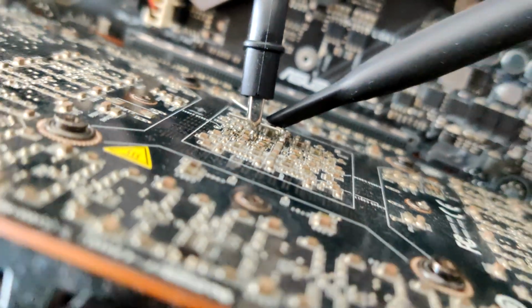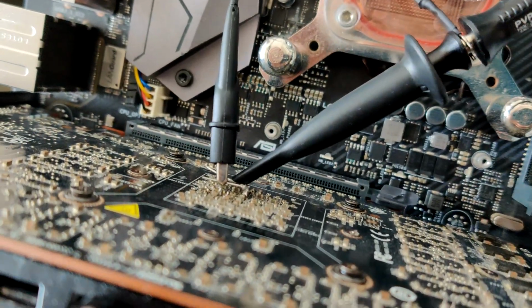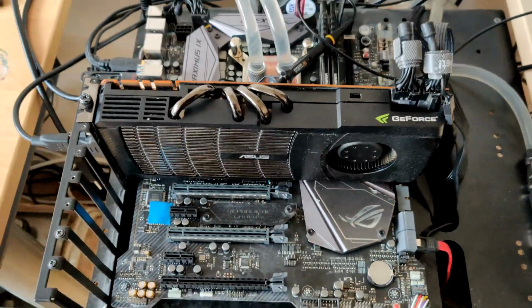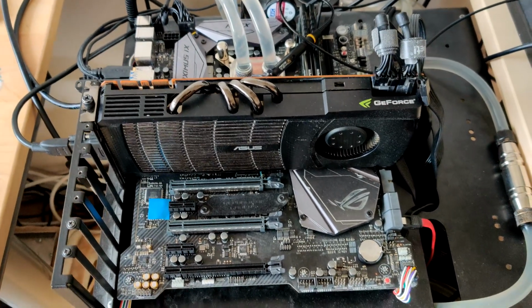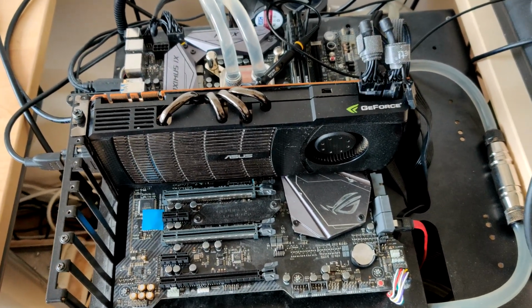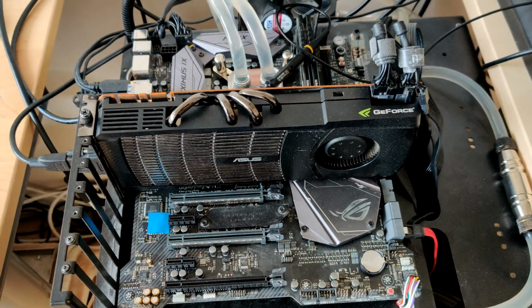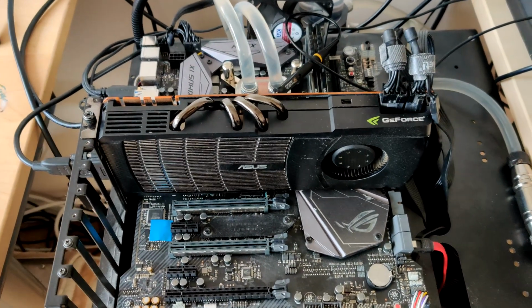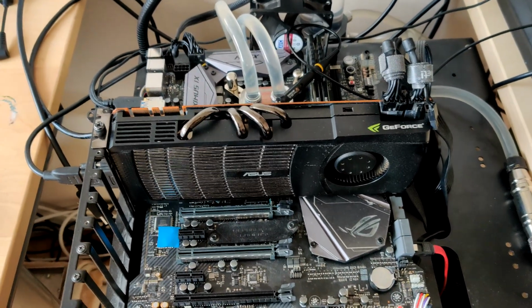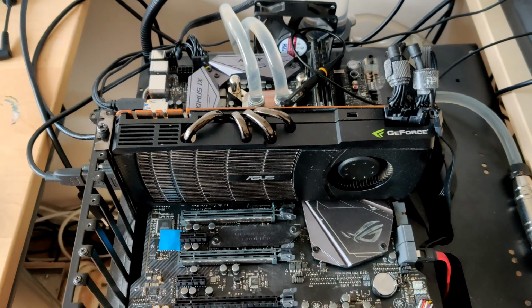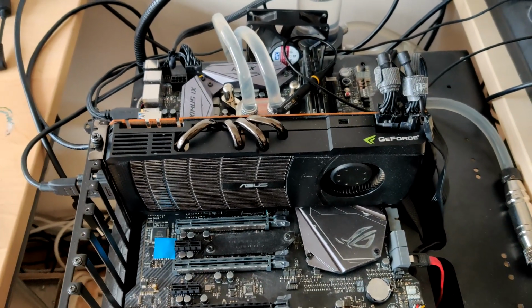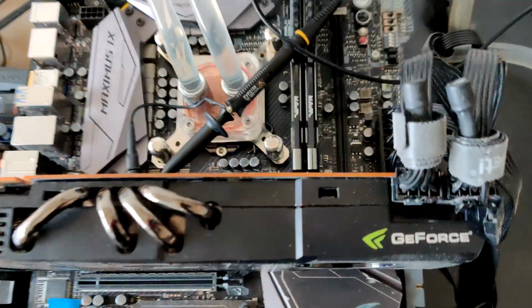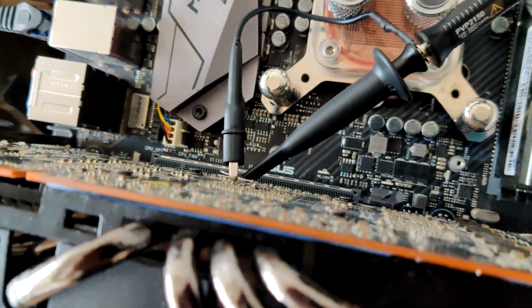So yeah, this is why I'm doing it on a 480 and not a 1080 Ti. But yeah, so the probe is hooked up to the V-core VRM of the 480 directly behind the core, which is reasonably the closest we can get to the GPU core to measure voltage, because due to power plane resistance and inductance and all the other physics things that are happening, our voltage does drop from the output of the VRM to the part we're actually trying to power, so we want to be as close to our power consuming part as possible. And on graphics cards, the backside of the core is usually the spot to go.